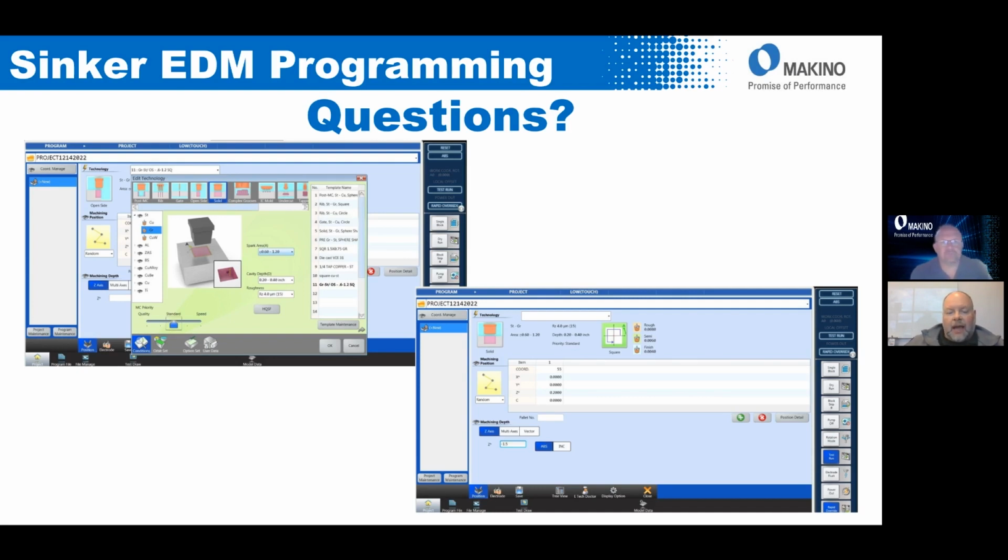Then we go back in with positive polarity and the electrodes after, second, third, fourth, depending on how tight we're going to hold that gate. So negative polarity has some good features, but on the other side of it, there are some negatives on the electrode wear side. So knowing when you want to use negative is definitely a good thing in the sinker, a good technique to use in certain areas of the process. Okay, good.